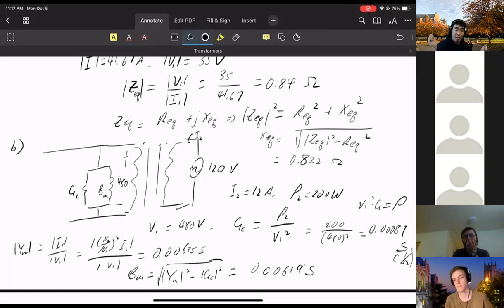Basically, the idea is correct. I need to synchronize a clock, so that we can both do sinusoidal measurements at different buses. As long as we have a perfectly synchronized clock, then it's fine. Because I can look at my sinusoid to see when it crosses 0, look at the other sinusoid to see when it crosses 0, and measure the difference in time. That gives me the phase information, because I know this is a 60 hertz system. So an atomic clock is one way to have synchronous time. Turns out that's a little bit expensive.